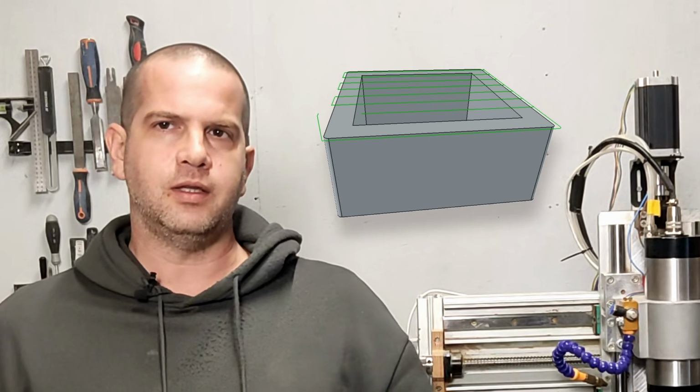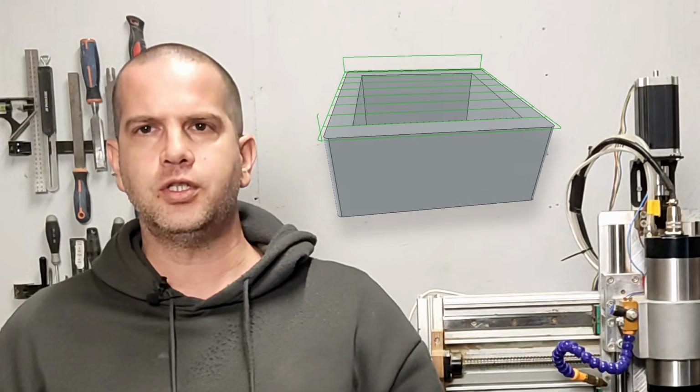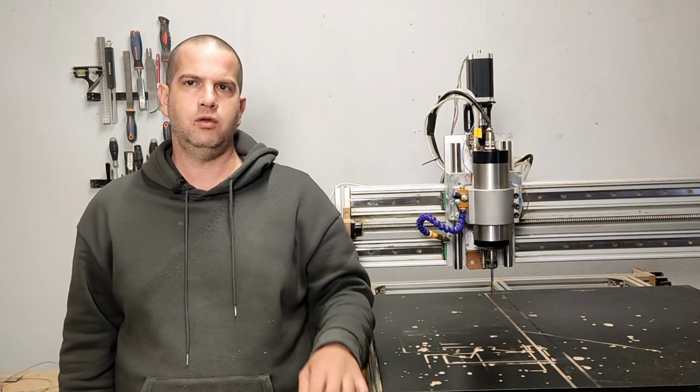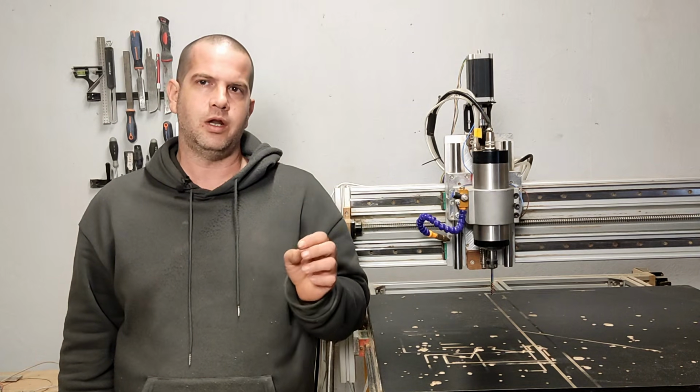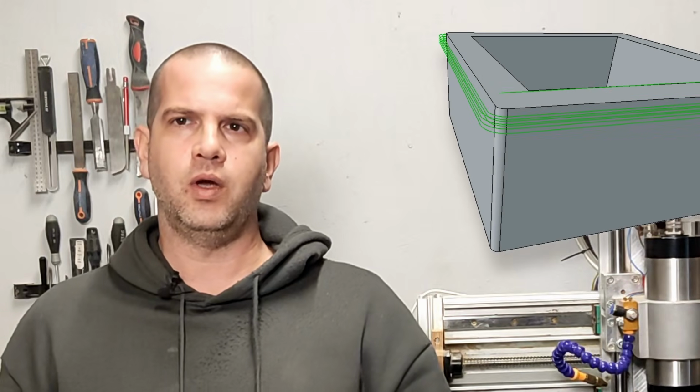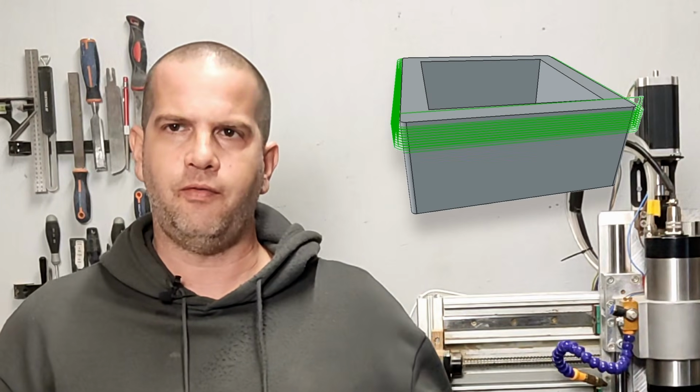In this video I will show you how to first model the object in the Part Design workbench in FreeCAD. I will show you how to make the toolpath to flatten the stock to bring it to the required dimension. After that we will create the operations to mill this pocket using two stages, one with a larger toolbit and one with a smaller toolbit. The next step is going to be milling the round holes using a Helix operation, and in the end we are going to mill the outline, the profiling of the object to get the shape that we want.